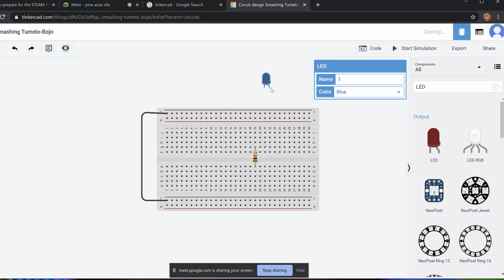So the LED, I'll explain to you what an LED is. It stands for light emitting diode. So think about it as a light bulb. When you put some kind of current or voltage, and I will talk later on about what is voltage, what is resistor, what is current. So for now, think about current coming through here, and notice that one leg is kind of crooked and it's longer normally. Okay, that leg is called the anode. That's where current should go through first. Okay, and it leaves the other terminal, the other leg, which is shorter, and it's called the cathode.